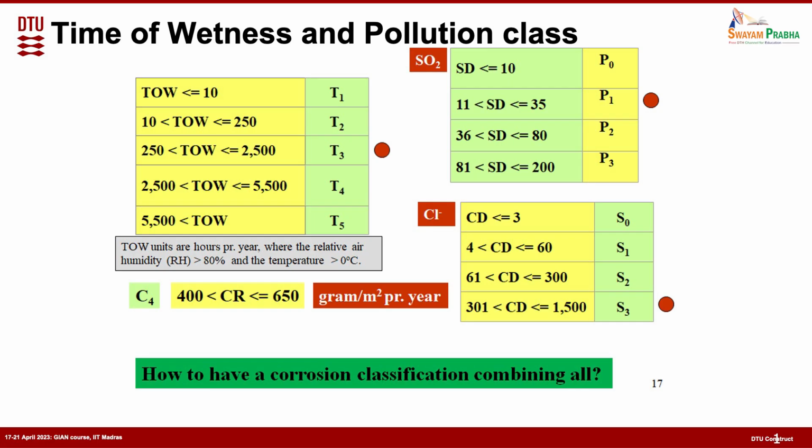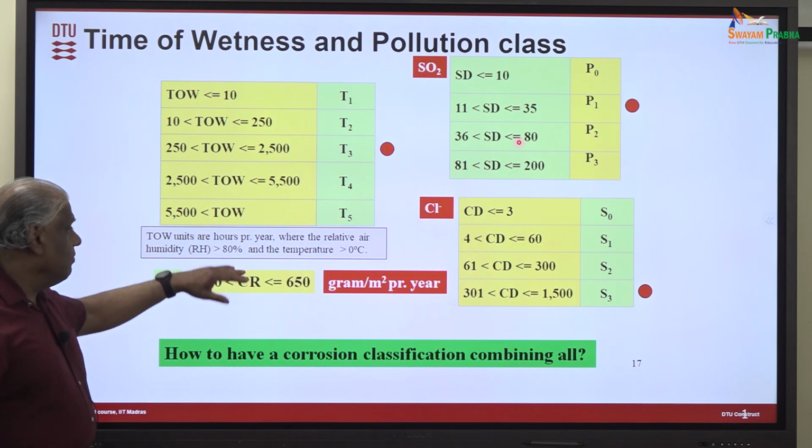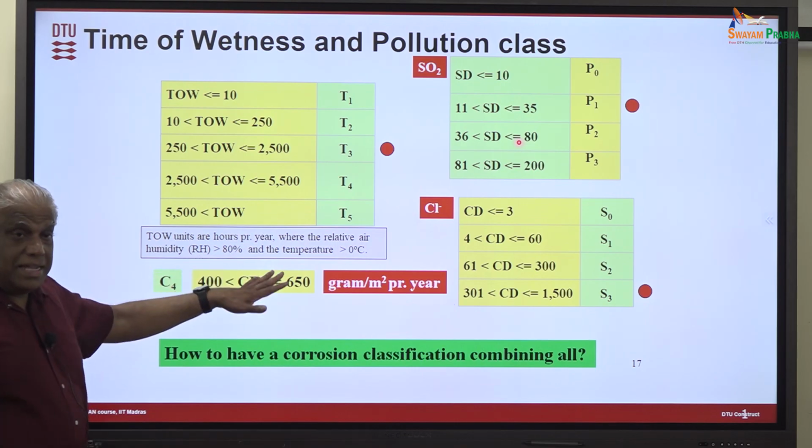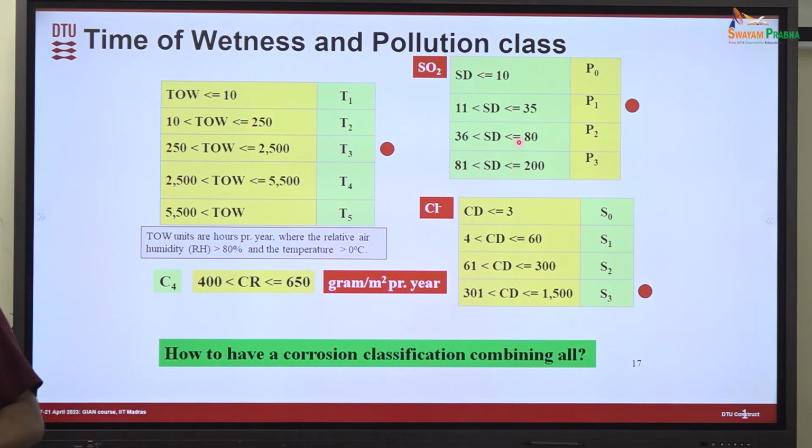Taking chloride as the common contamination which you see at most places, that's because seawater contains a lot of sodium chloride. Sodium chloride is one of the main contaminants you see on surfaces, causing atmospheric corrosion. Taking that as a basis, the deliquescent point of sodium chloride is below 80. So if your humidity level is higher than 80, there is a chance for water film formation on the surface of the material.